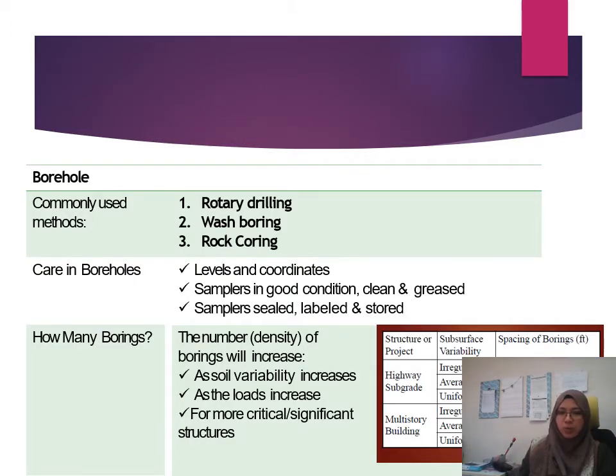Okay, care in boreholes. So you have to check the level and coordinate. So every borehole that you have made on your ground, on your site, you have to check the level, okay, and then you have to check the coordinate, right? And then sampler, so you have to check all of the sampler in good condition. It must be clean and greased inside. And then sample must be sealed, labeled, and stored.